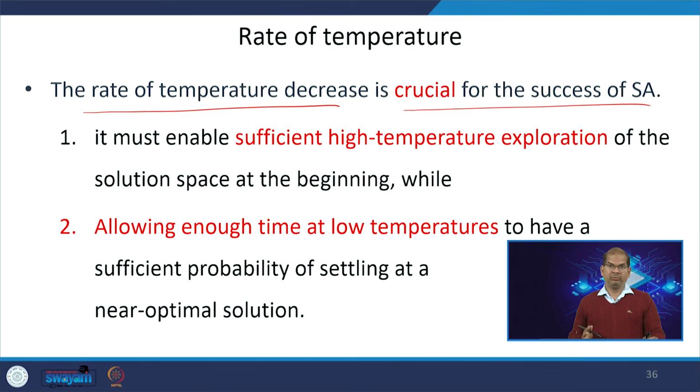Remember that simulated annealing is the most popular algorithm in VLSI physical design. It is used quite frequently at different parts of physical design to optimize various objective functions, because it is a heuristic driven algorithm and not a greedy algorithm.